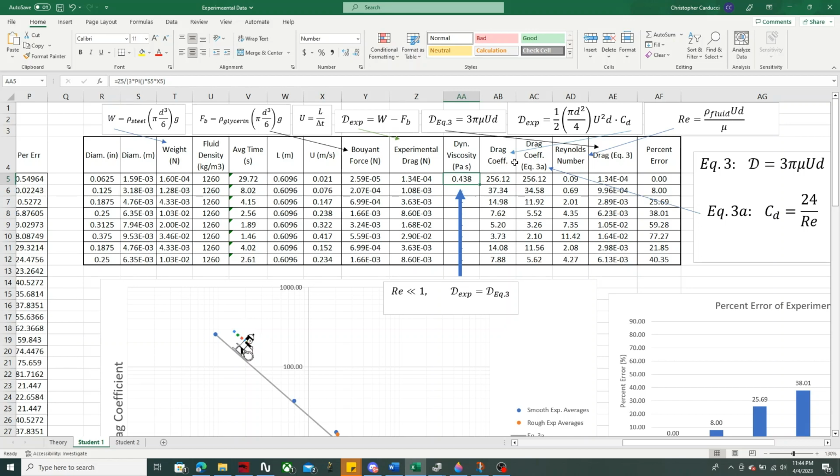So, how do we find your drag coefficient? Well, once again, you have your experimental drag. All you're going to do is rearrange this equation, your semi-empirical equation, to solve for your drag force, right? And that's it. Your drag coefficient is an empirical quantity that you just get from doing experiments over and over and over again, right?